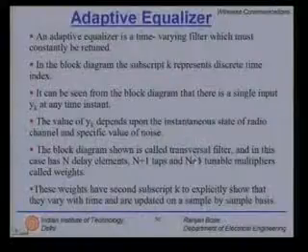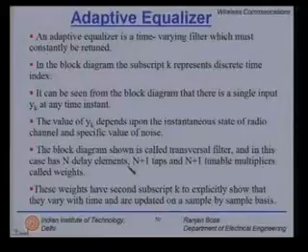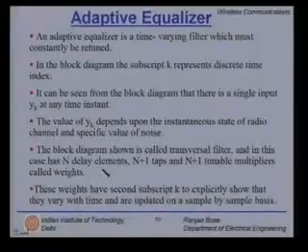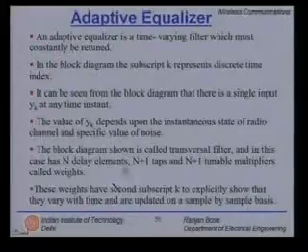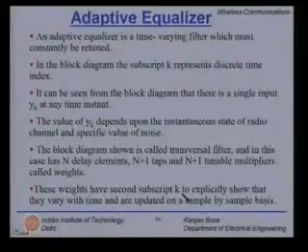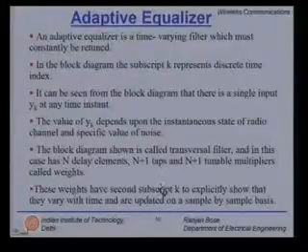But in general, the block diagram shown just before, which is called a transversal filter, has n delay elements and hence n plus 1 taps, and consequently n plus 1 tunable multipliers, which we will call weights. Now, these weights can be complex weights. As pointed out earlier, the weights have a second subscript k to explicitly show that they vary with time and must be updated on a sample by sample basis or a block by block basis, that is for the whole weight vector.